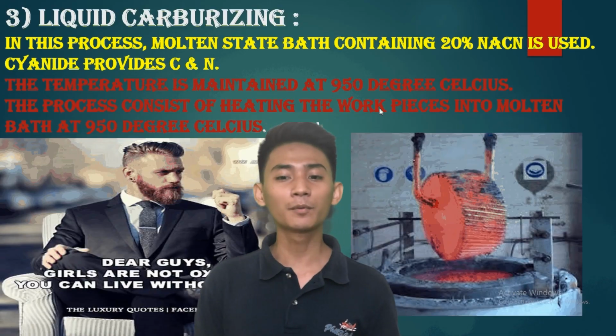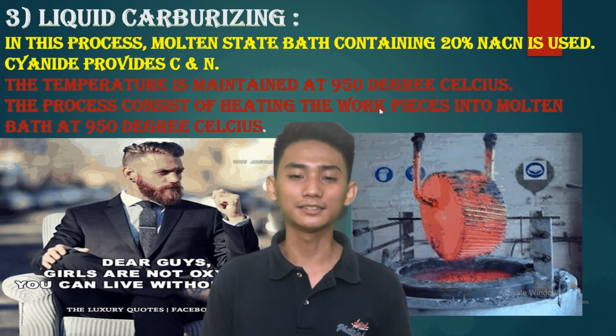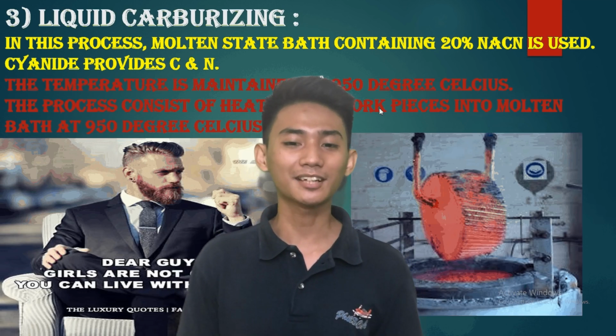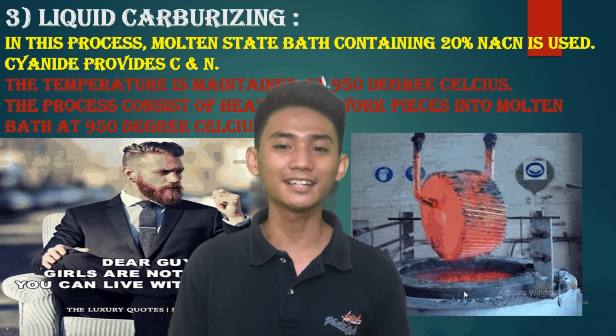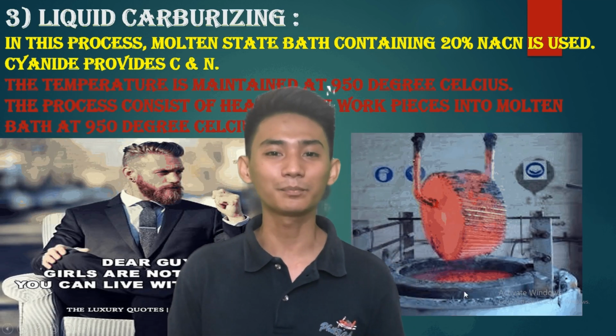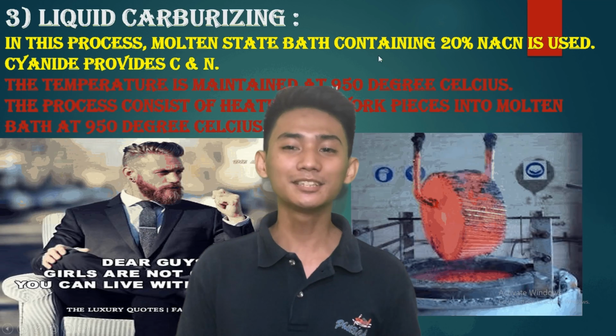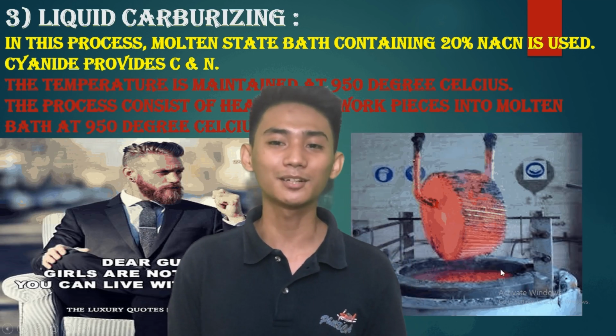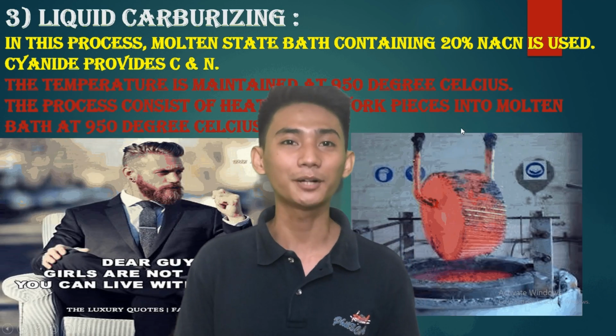The third method of carburizing is that of liquid carburizing. In this method, the steel is placed in a molten salt bath that contains the chemicals required to produce a case comparable with one resulting from pack or gas carburizing. This produces a high carbon surface when a part is heated in a molten salt bath of sodium cyanide or barium cyanide. Lastly, under case hardening, we have nitriding.